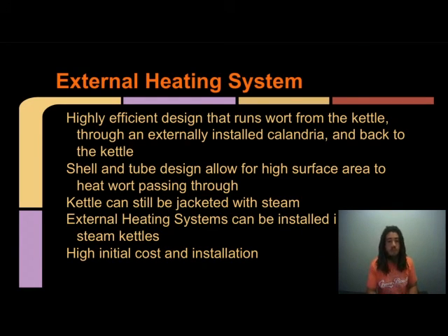External heating systems can be installed into existing steam kettles, which is kind of the beauty of external heating systems versus internal. You can build a brew house without an external heating system, and if you find you need one, you can attach one. It's a changing of the piping and installing of this, moving some steam to it, assuming that your boiler is big enough to pump out that much steam for the kettle and for your external heating system. But that is always a nice thing about the external ones. You can install it whenever. It does, however, have a very high initial cost, and the installation is not cheap as well.